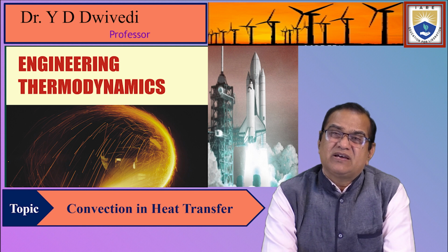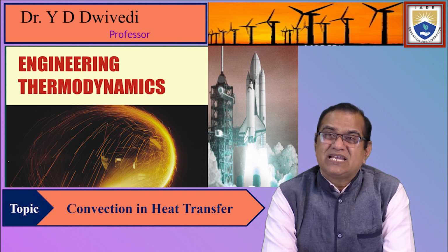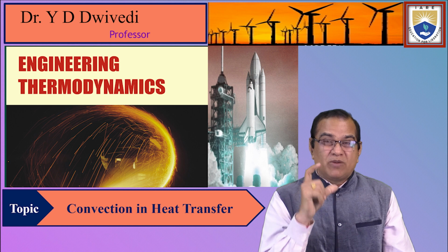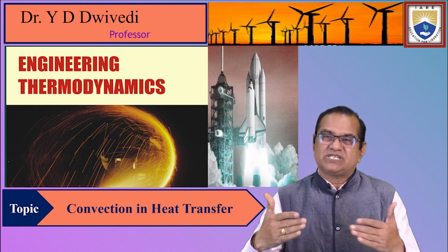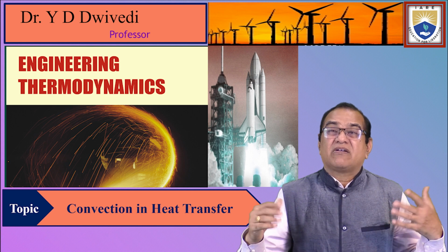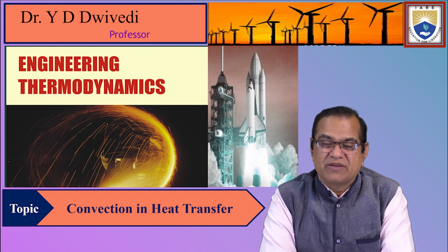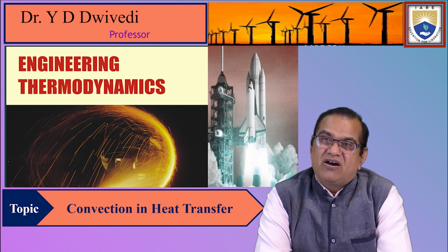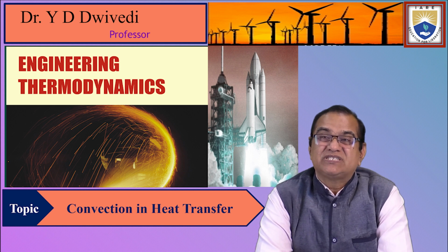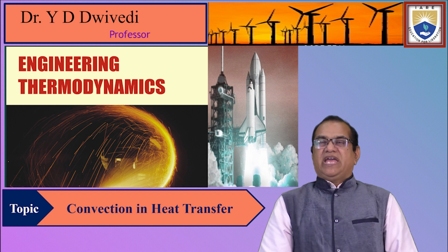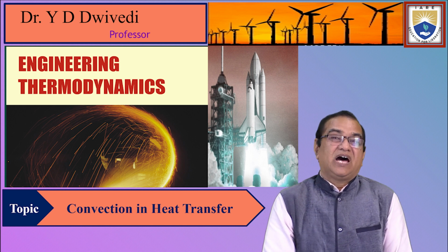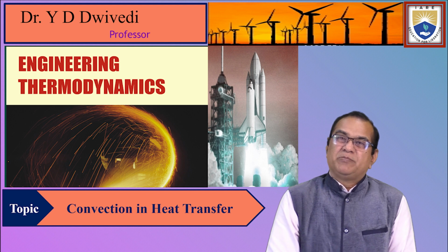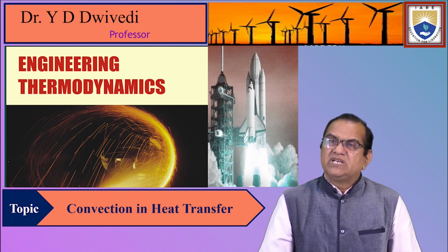If you see the intermittent, the Otto cycle, diesel cycle, dual cycle, these three are not producing continuous power. Out of 4 strokes, they are producing 1 power stroke. But the Brayton cycle is a continuous process, where continuous power is generated. So it is a rotary type, and the other is the reciprocating type. Another is the power absorption or work absorption cycle, which is the Bell-Coleman cycle, used for air conditioning and refrigeration. The power producing group is used for heat engines like piston engines or turbo engines.